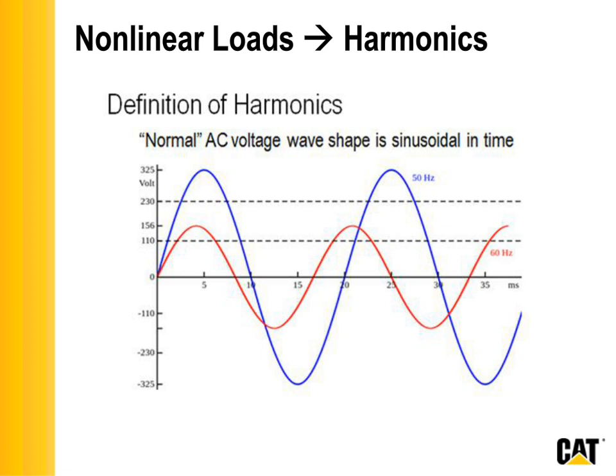The exceptions were resistive load and three-phase motor load, but some of the three-phase motor load starters are nonlinear. So almost everything of those 19 current loads in SpecSizer, almost every one is a nonlinear load. Nonlinear loads create harmonics, they create distortion. That's a bad thing, okay? Especially if you have an application like a data center. So what you want is for your sizing tool to be able to mitigate the harmful effects of those nonlinear loads, the harmonics and distortion.